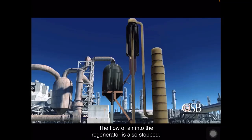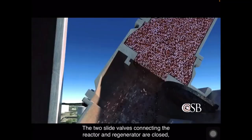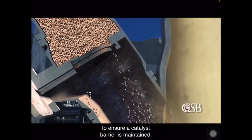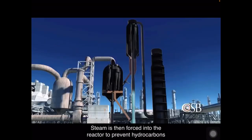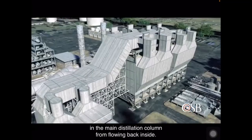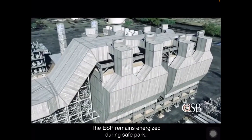The flow of air into the regenerator is also stopped. The two slide valves connecting the reactor and regenerator are closed to ensure a catalyst barrier is maintained. Steam is then forced into the reactor to prevent hydrocarbons in the main distillation column from flowing back inside. The ESP remains energized during Safe Park.